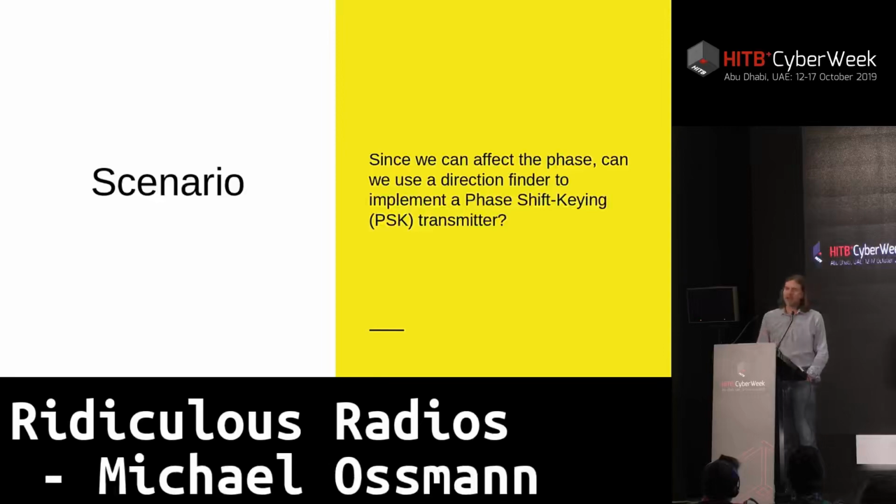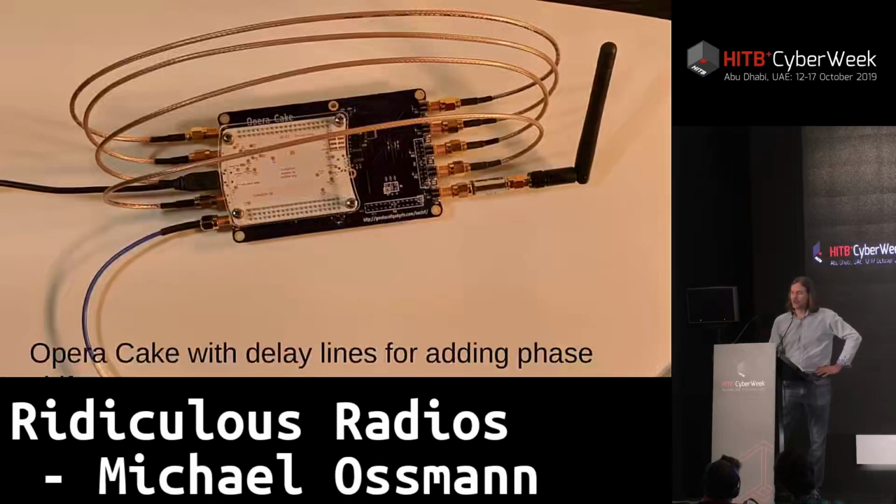Because if he can do that, then he can actually create a covert channel. He might have his Bluetooth dongle transmitting using frequency shift keying or on-off keying or some other technique that it maybe natively knows how to do. But then he can also add a hidden layer of modulation on top of that signal. We thought that was very interesting, kind of a way to create a covert channel on top of a radio signal that you might be normally using or allowed to use.